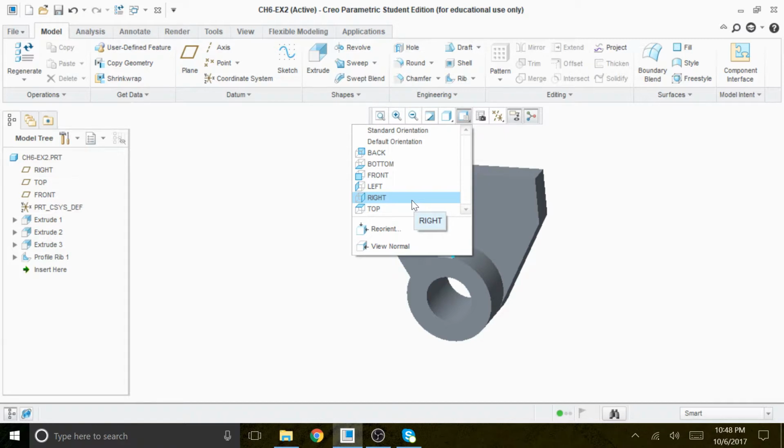If it has more of a cylindrical shape, the projection is going to be the same in either the right side view or the top view. So we decide whether to show them, but the front view is a must. You must show the front view, and then for the right side view and top view, you have to make a decision: do you need all 3 views, or only 2 views?